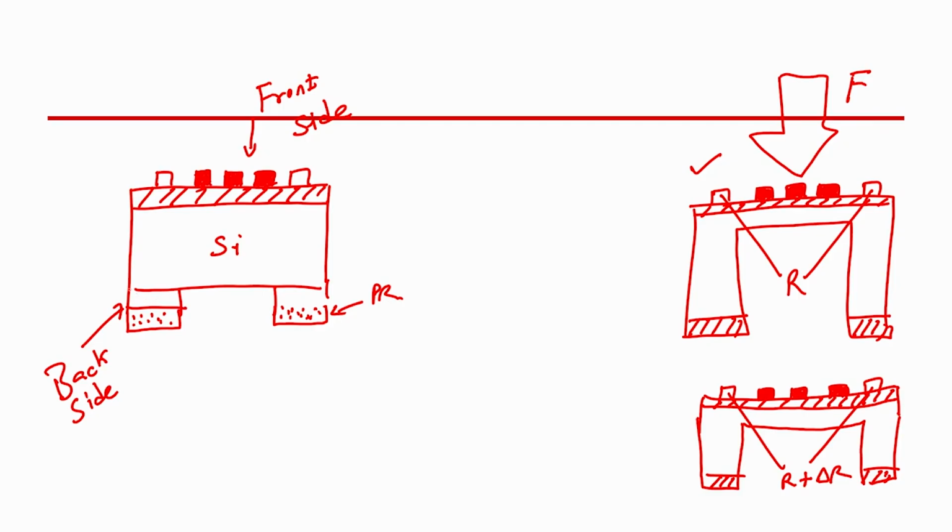My silicon dioxide gets etched from the area which was not protected by photoresist when I dipped that wafer in buffer hydrofluoric acid, BHF.